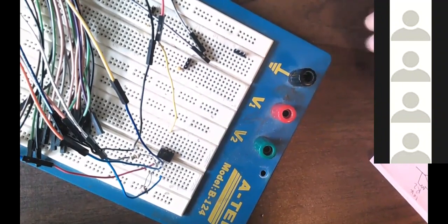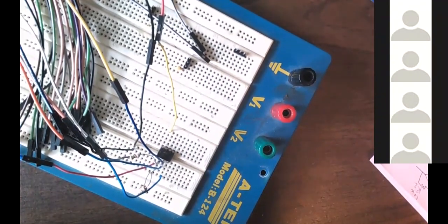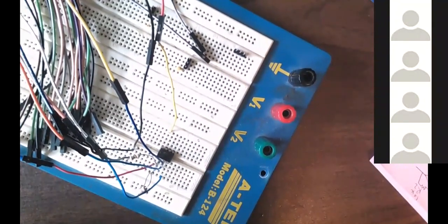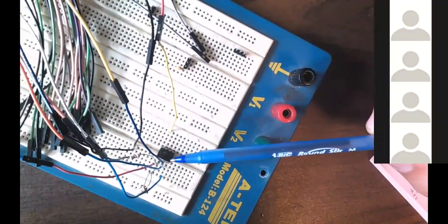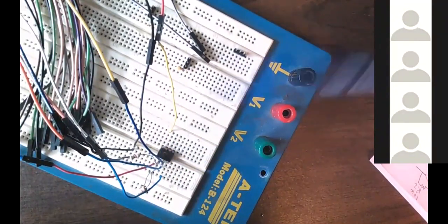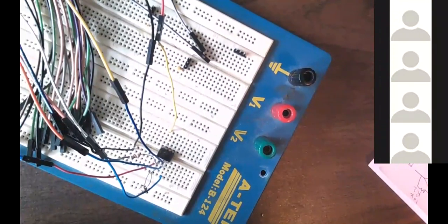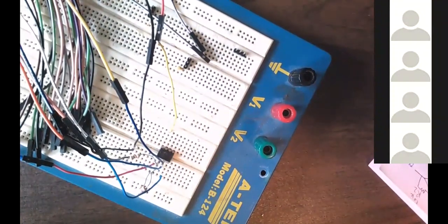I only use the bottom half. That's 1 op-amp. The circuit is identical to the non-inverting amp we just studied. So the input will be 1. The gain will be 11. So if my input is 1 and the gain is 11, the output will be 11, right? That's in theory. So let's find out what will happen.